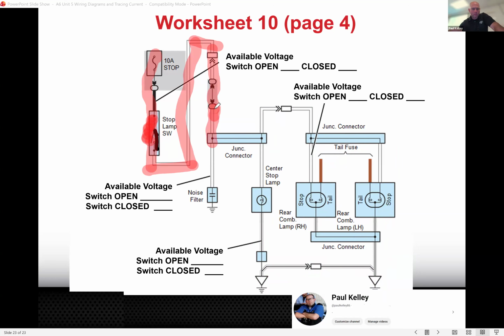No, so the 12 volts should keep going. Now, I don't know exactly what's going to happen there with that capacitor, but we won't worry about that because that's not going to make our lights not work. Okay, so red, we go here. It would stop there because that's a load, which means on the other side of that load, there should be 0 volts remaining because it's all been consumed.